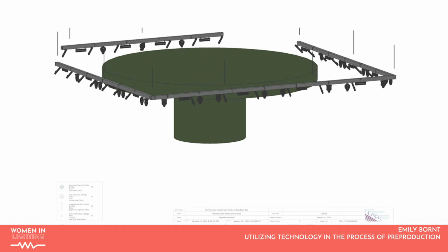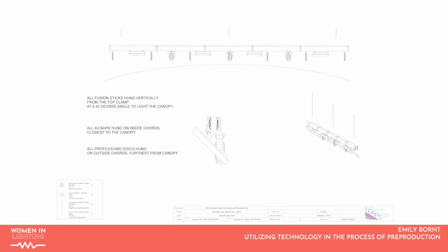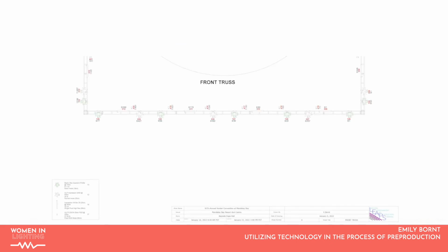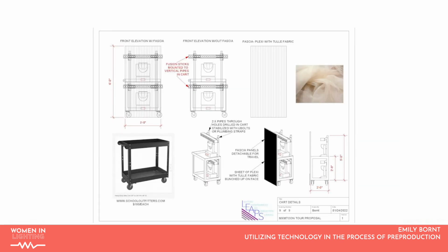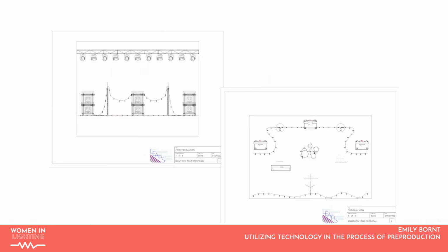You can also see in preliminary programming and making renders if you have the right fixture choices once things start shuffling around or evolving. Maybe you need a lower profile fixture to fit inside a set piece, or you need a fixture with a wider beam angle, or more of them to get the coverage you need. It can also be helpful to have your entire rig in 3D so you can play virtual Tetris and figure out if it actually will fit into the truck space you've been allotted.